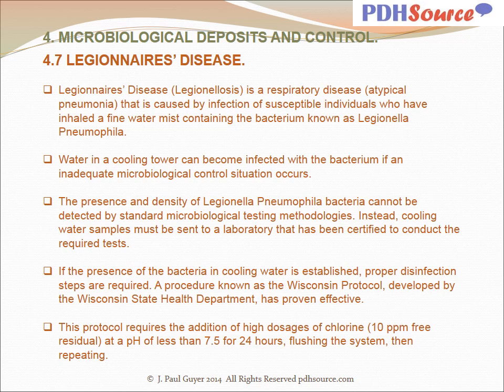Legionnaire's disease is a respiratory disease that is caused by infection of susceptible individuals who have inhaled a fine water mist containing the bacterium known as Legionella pneumophila. Water in a cooling tower can become infected with the bacterium if an inadequate microbiological control situation occurs.